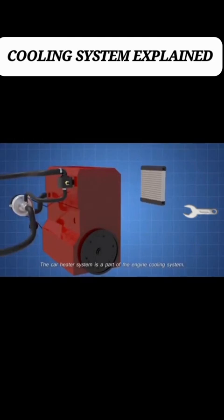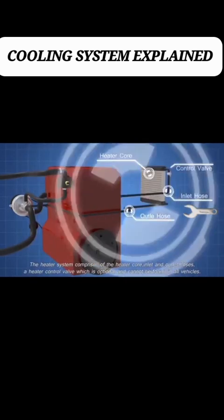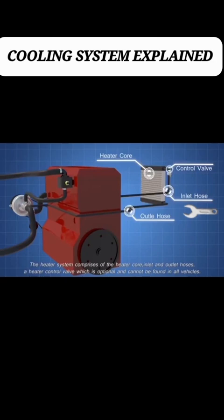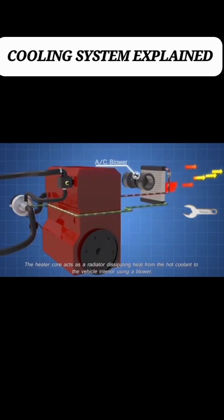The car heater system is a part of the engine cooling system. The heater system comprises the heater core, inlet and outlet hoses, and a heater control valve which is optional and cannot be found in all vehicles. The heater core acts as a radiator, dissipating heat from the hot coolant to the vehicle interior, using